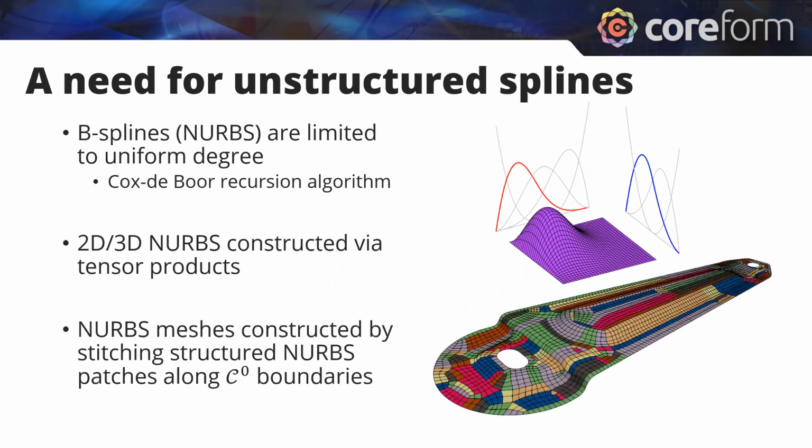But then also, if we build a mesh that's unstructured, that tensor product is inherently a structured layout. It has U and V principal directions. And so we could really only build smoothness over a single NURBS patch or B-spline patch, which I've colored here in gray. Some cases, right, I just ran out of colors.